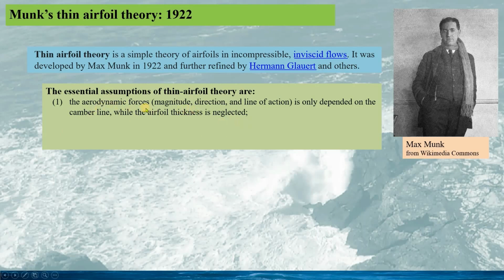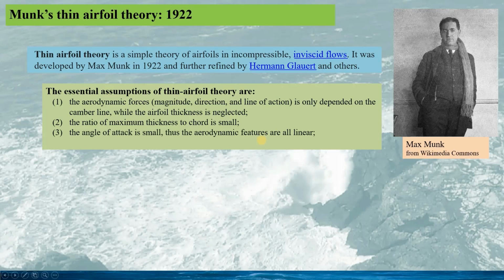For instance, the aerodynamic forces, including the magnitude, direction, and the line of action, only depend on the camber line, while the airfoil thickness is neglected. The ratio of maximum thickness to the chord is considered to be very small, and the theory only works for a small angle of attack. Thus, the aerodynamic features would all be linear.